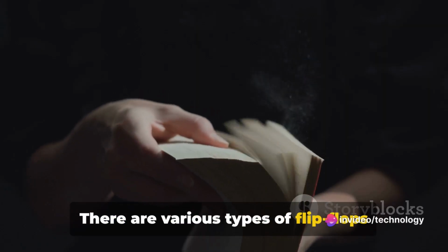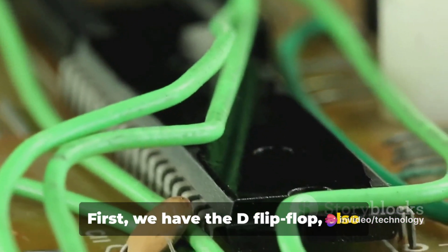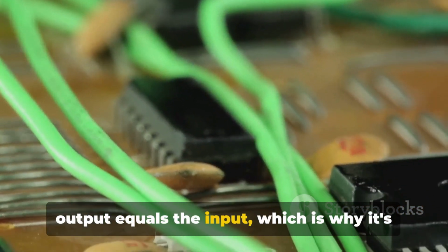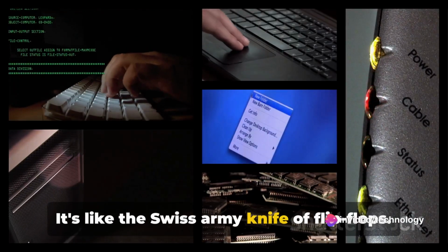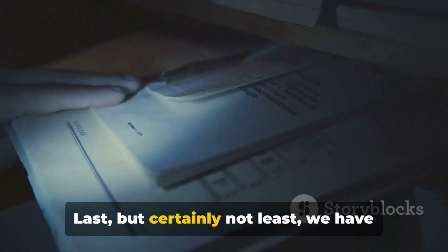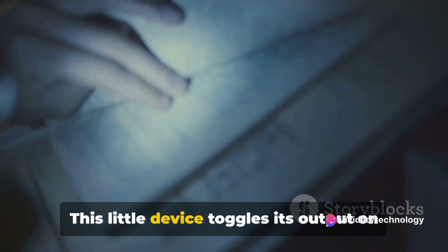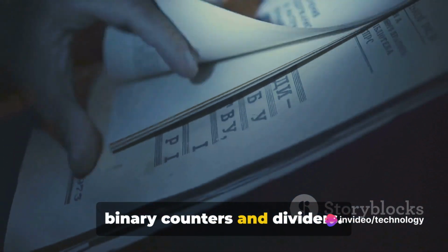There are various types of flip-flops used in sequential circuits. First, we have the D flip-flop, also known as data flip-flop. The D flip-flop has a property where the output equals the input, which is why it's often used for storing binary data. Then we have the JK flip-flop. It's like the Swiss Army knife of flip-flops. It can function as any other type of flip-flop, making it incredibly versatile. Last, but certainly not least, we have the T flip-flop, or the toggle flip-flop. This little device toggles its output on each clock cycle, making it great for binary counters and dividers.